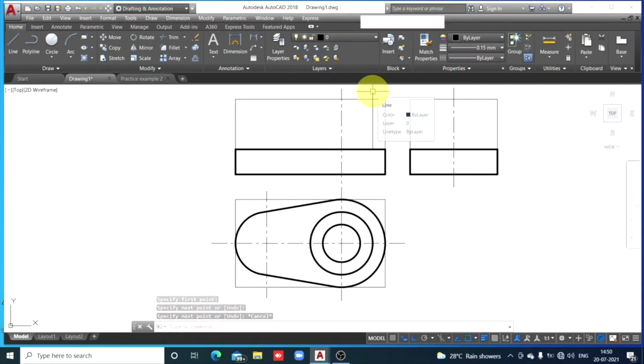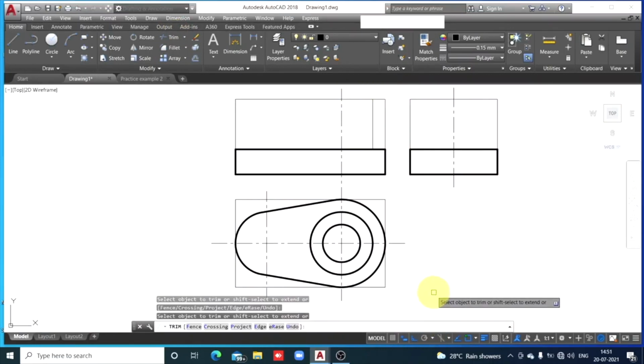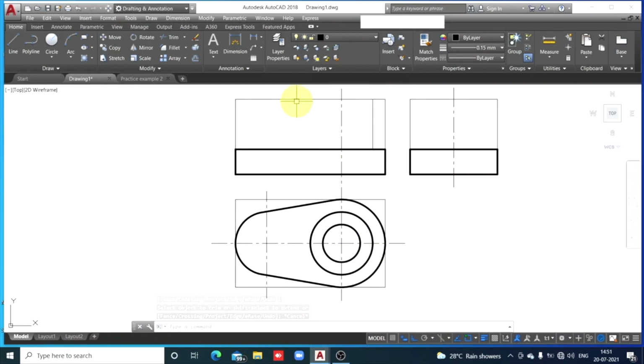So you have got extra length for this line, that extra portion to be trimmed. So click here, trim, enter, and then remove that portion. So the cylinder is above the base plate. The height of the entire object we have already measured as 60. Out of 60, 20 millimeters is the height of the base plate, and above that 40 millimeters is the height of the cylinder. Similarly, now watch here. I have selected the line command and I am now tracking the left end of the cylinder.